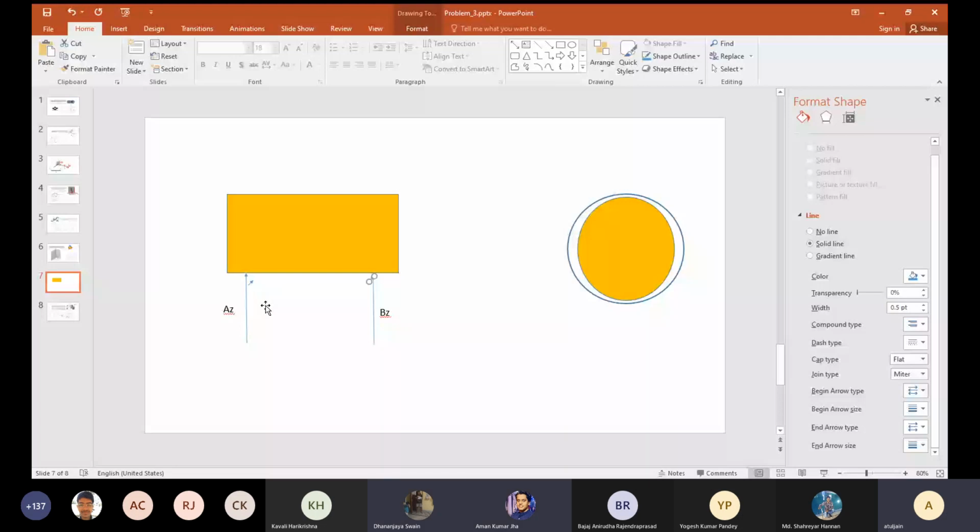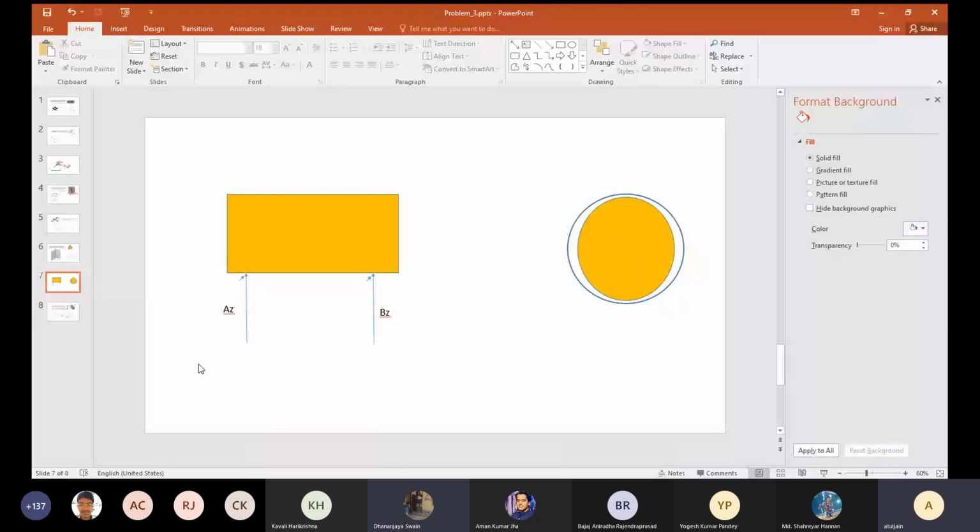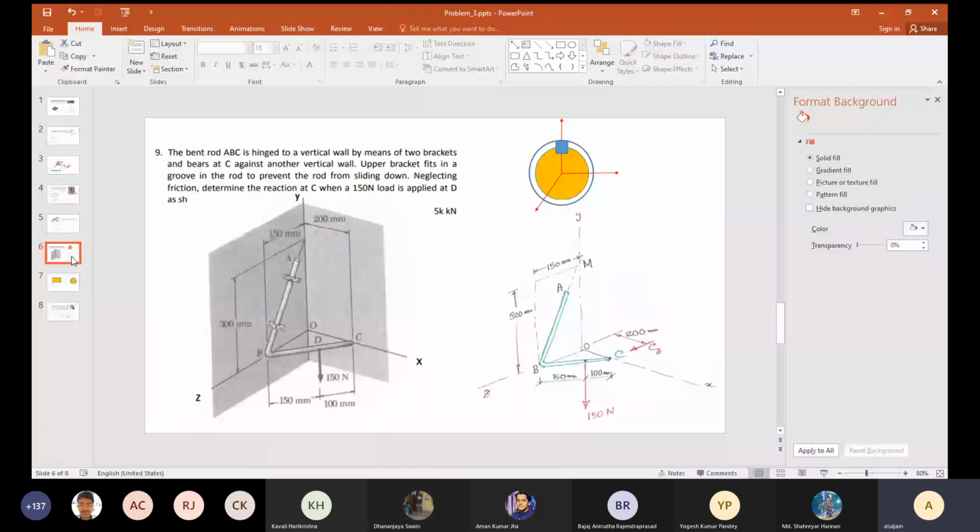Sir, in what rare cases do we have to look at both constraints? I think Professor Sushanto Chakravarti must have talked about it, when he was talking about links. There are some specific cases where you look at both. Otherwise, in general, this approach will help you: look at only one constraint at a time, draw the free body diagram subject to that constraint, and take it forward from there. Do not worry about what the other constraints are. Sir, there will be no moment about any of the groups? No, because it is allowing rotation.